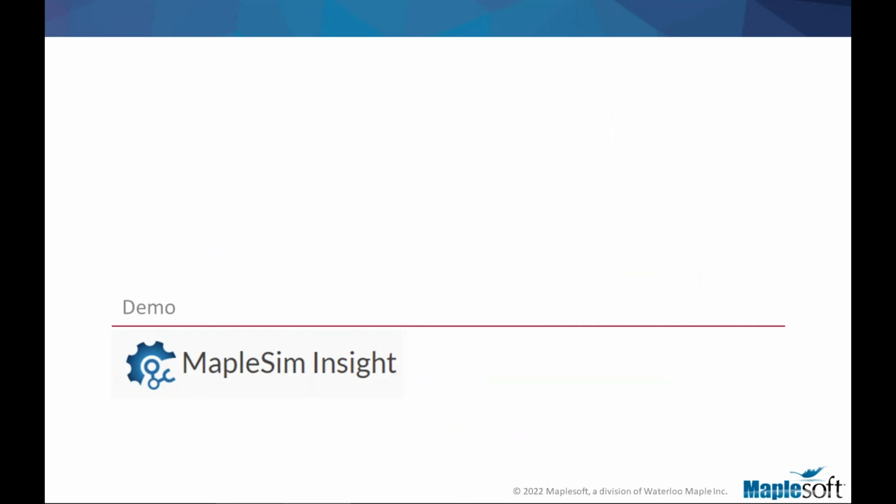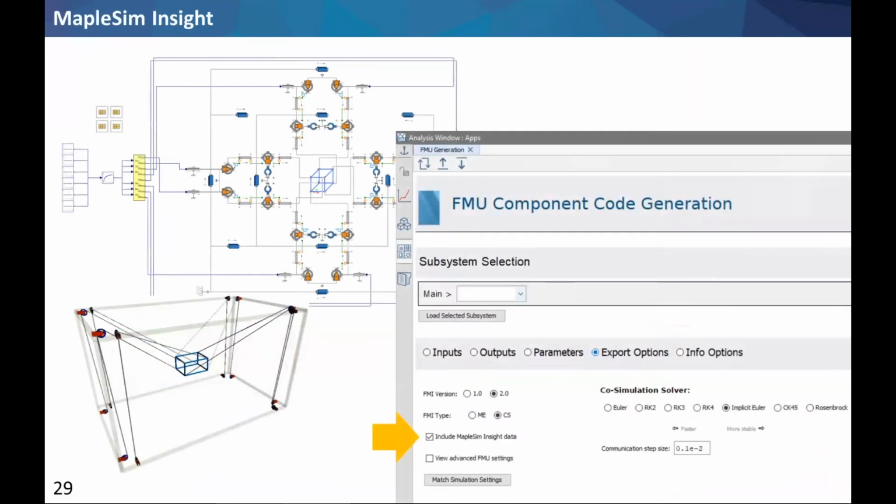The last example that I have is taking this to the more detailed. And for that, I have included the FMU. So all models we create in MapleSim, you can export them as FMU, and that FMU is the gateway to incorporate that in other parts of your tool chain, whether it's an automation case or other projects that can understand FMU. We can also package our models in just pure C code or other formats, but FMU being popular and becoming more and more popular each day.